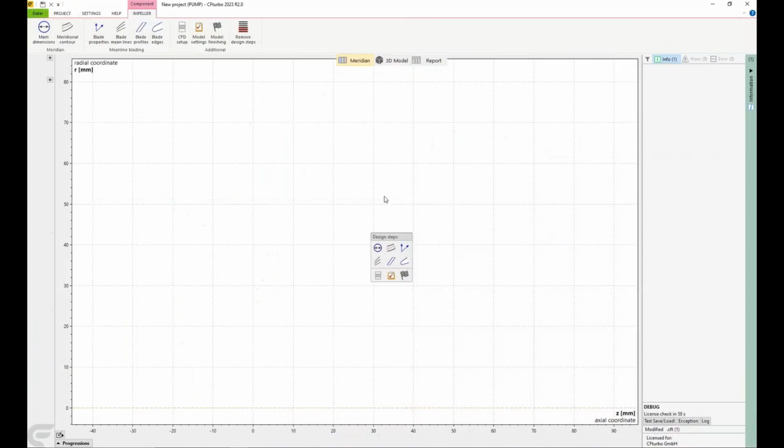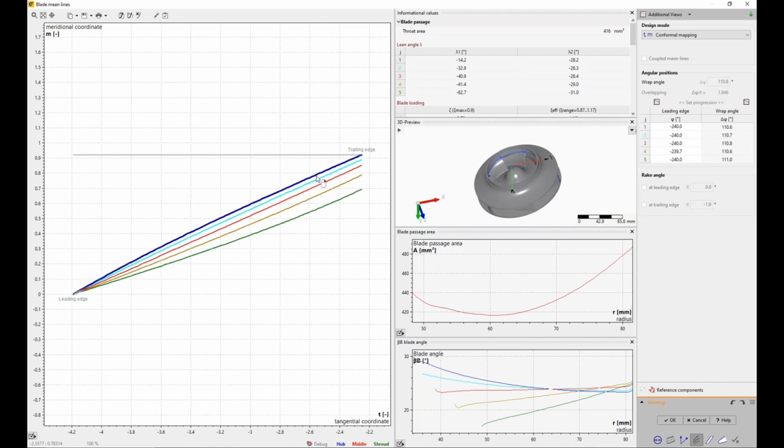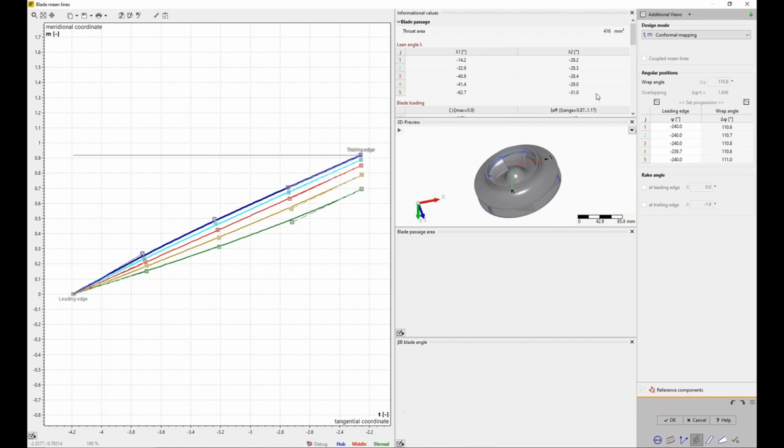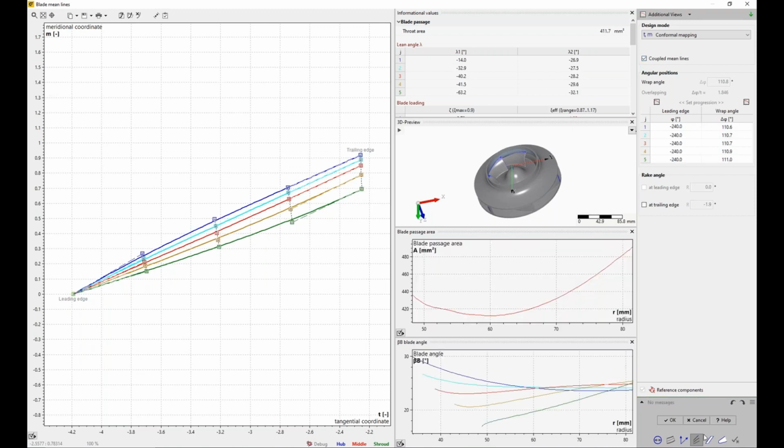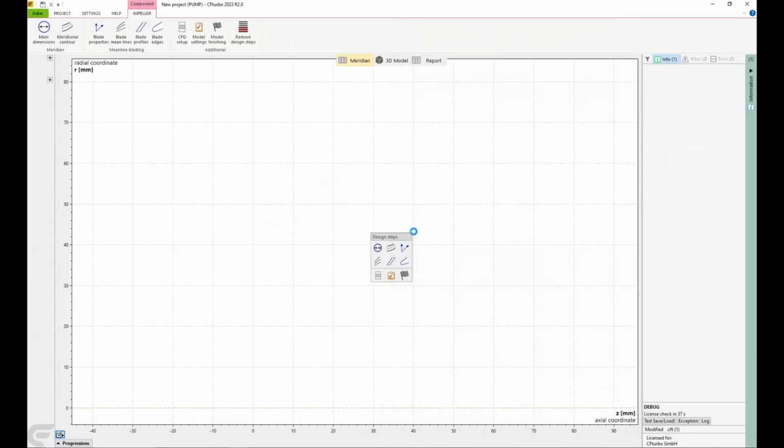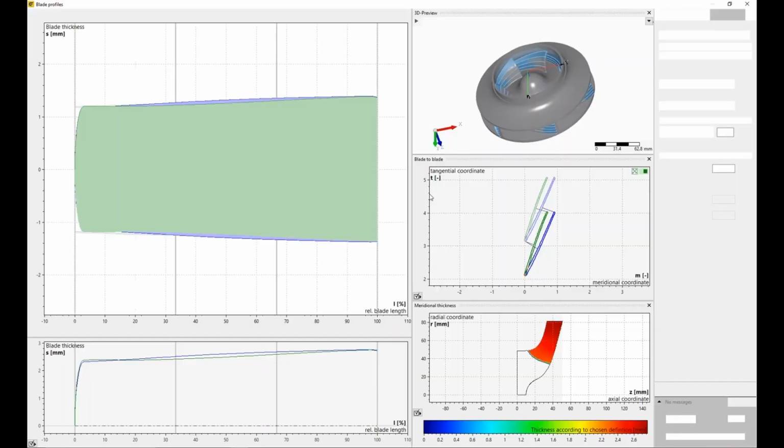And the same could be done for the camber or mean line. And if I do that, then I get really a parametric model, and after I have finished that, I can start, for instance, automatic optimization or something like that, DOE and so on. Okay, and after a couple of measures, I have a fully parametric description of the primary flow path.